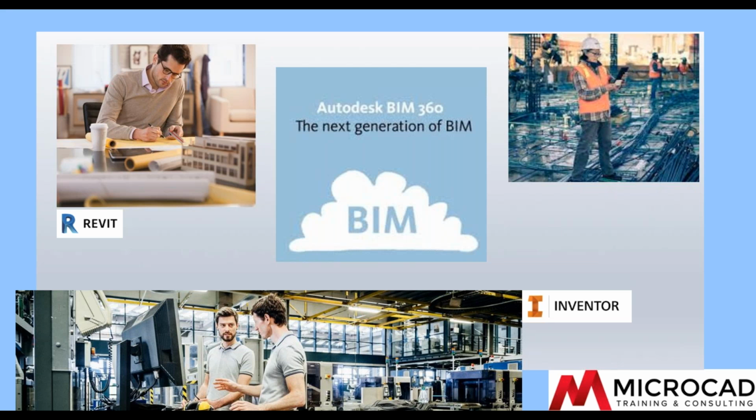Let's see what more questions we have. Yeah, so somebody pointed out that they don't want to share intellectual property, that sometimes in their design work they've added their own knowledge that they don't want the architect to have. Well, that's perfectly fine, because in Inventor you have the ability to not share certain information into the Revit family. So when you build your Revit family to go back to the architect, you would simply exclude the information and the parts that are your own IP that you don't want to share. And again, we'll see that next week when we do that webinar and the details.